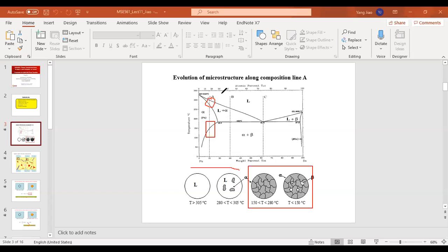Sorry, I should use a different color. But anyway, you see that the first solidification scenario we analyzed is basically like this: the normal nucleation and growth processes. And then we focused on this branch where we talk about eutectic transformation, which is also a commonly seen transformation pathway that takes you from liquid to solid. So these are the two solidification cases in alloys, and we already discussed both of these distinct cases. So we're basically done with the solidification part.